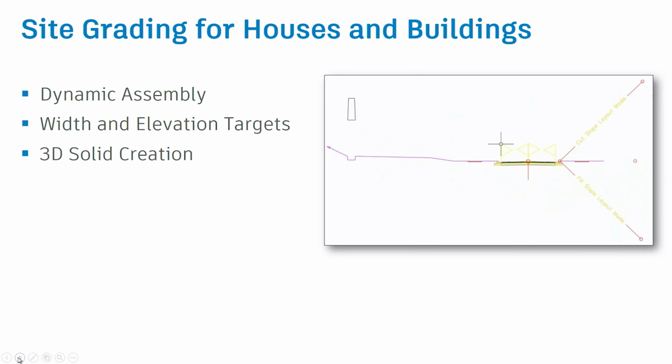So in Civil 3D, we can leverage the power of corridor modeling, and we can do it for more than just making a path. In this particular case, the reason I want to use a corridor model is because it's extremely flexible and very, very dynamic. And it has built-in conditionals and also built-in attribution that allows us to do things like quantification and materials. So we're not only doing the road center, but we're also going to grade out the lots, the building lots, the building pads.